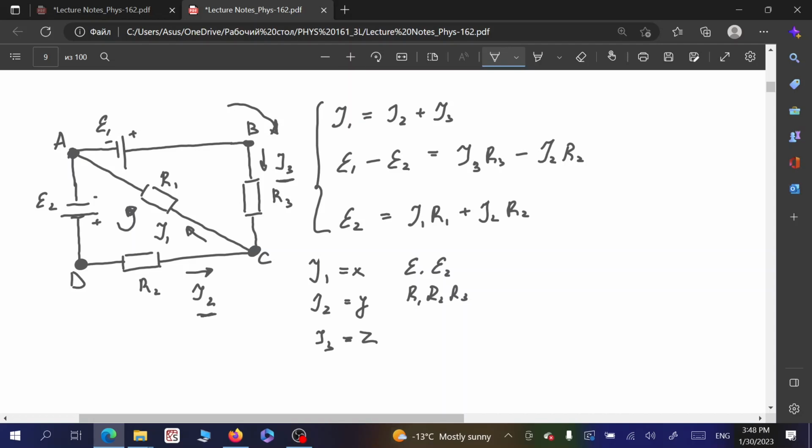So the potential difference at the terminals of the battery will be different in the working electric circuit, then the internal electromotive force. And we also have shown that in order to get maximum electric power dissipation over the load resistor, its magnitude should be equal to the magnitude of the internal resistance of the battery.